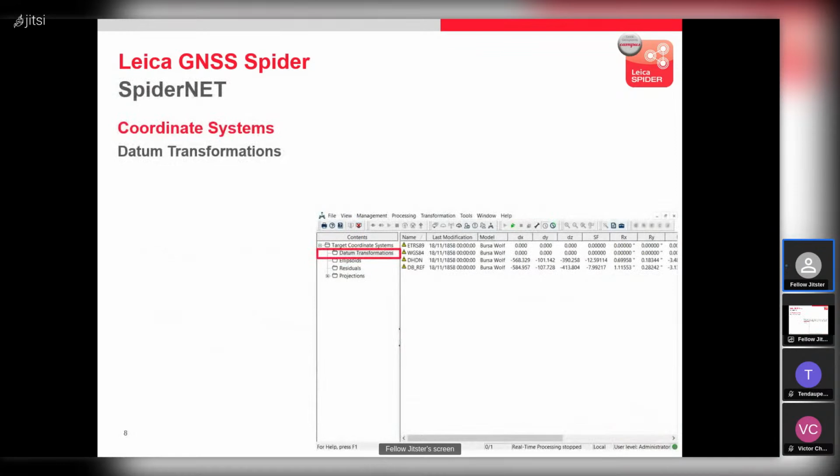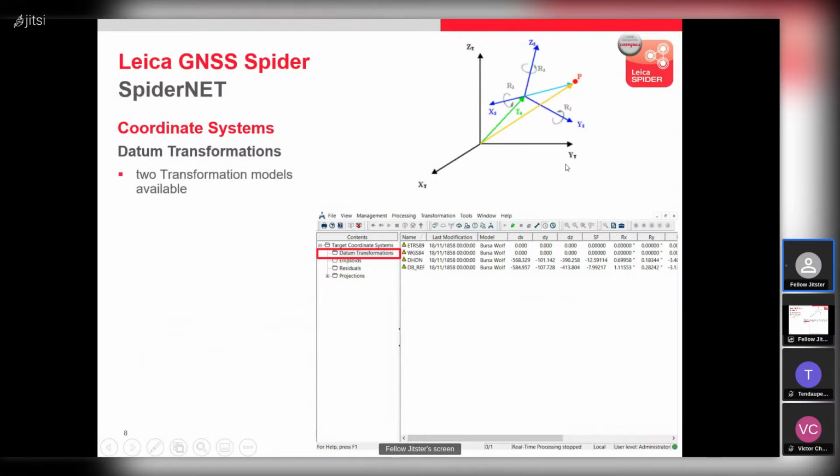So the first thing to define is this transformation. Something you have seen, something similar. This is the principle of transformation: if you want to go from this XYZ to this blue XYZ Cartesian, you need to shift the origin. So typically these three shifts in the X, Y, Z components. Then you need to rotate each of the axes, and then scaling, if necessary, can also be applied.